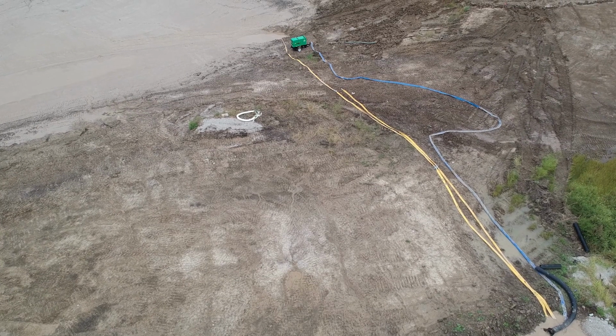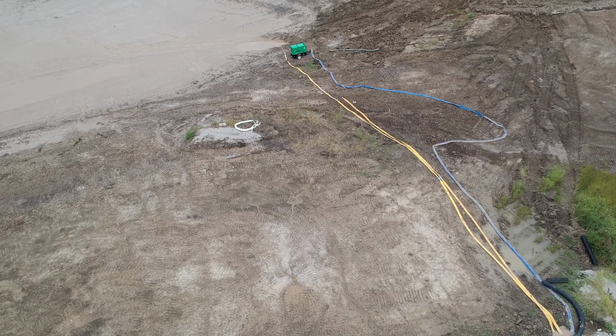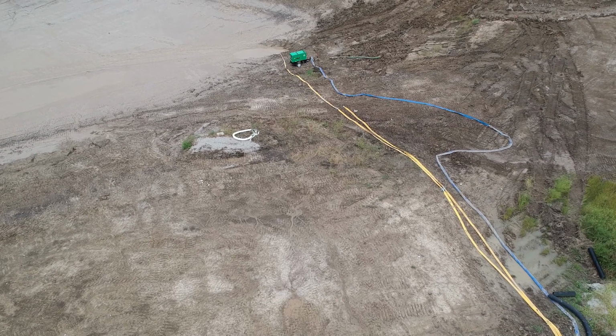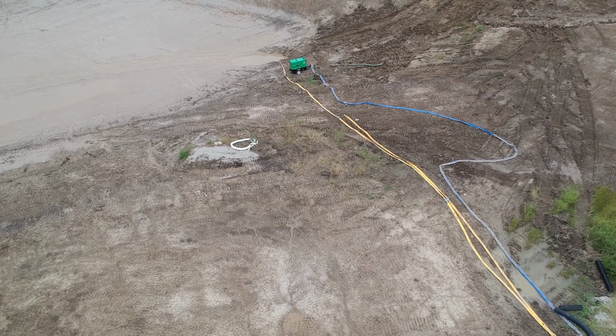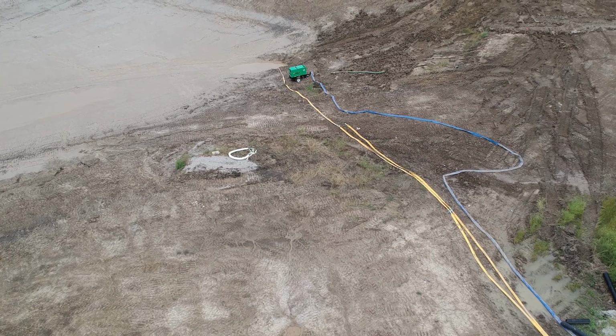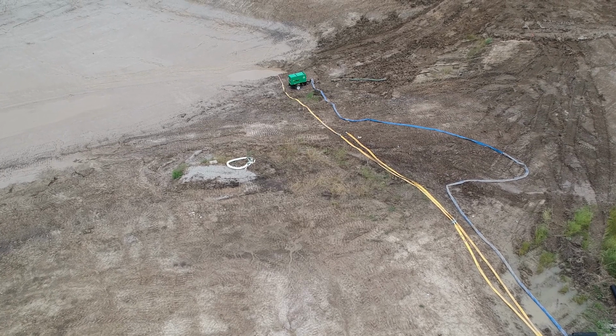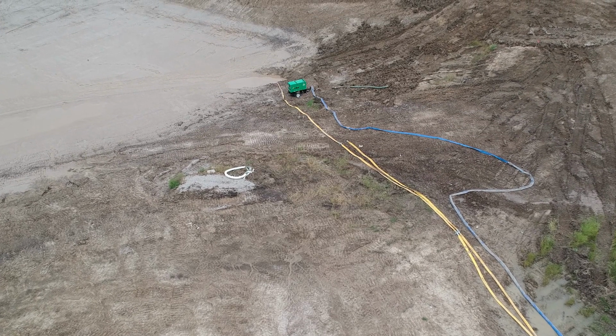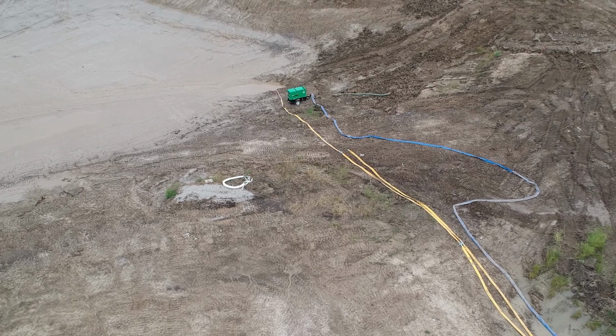Pipes, casings, and any other material used to dewater the site shall be removed from temporary wells, which are then filled to ground level with clean gravel or other suitable material approved by the contracting officer. The contractor shall exercise extreme care to prevent pollution of the groundwater by these actions.